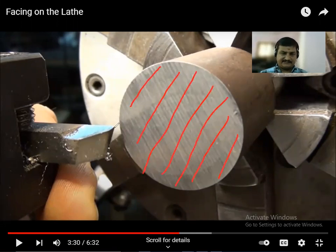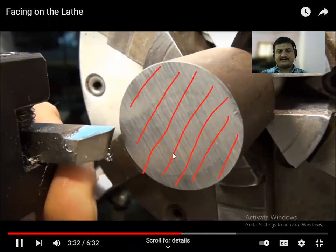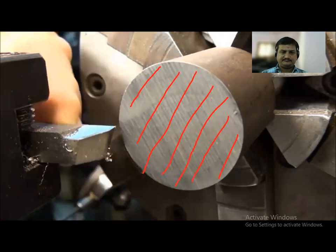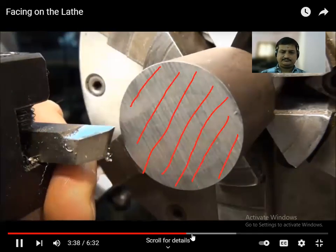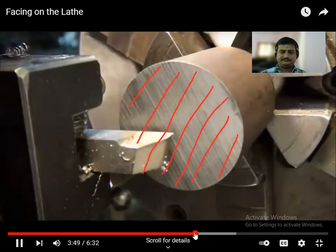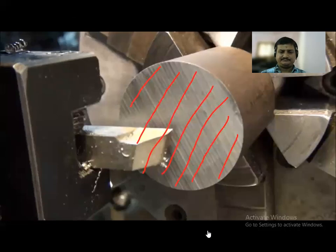Okay, and here the single point cutting tool is fixed to the tool post. When the operation starts, angle it about 10 to 15 degrees, just to check what is going to happen. Give this area a little bit of clearance on the end, so only the tip of the tool cuts. So just kind of eyeball it to start.